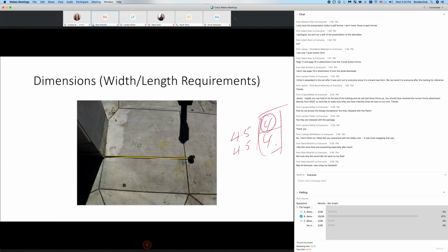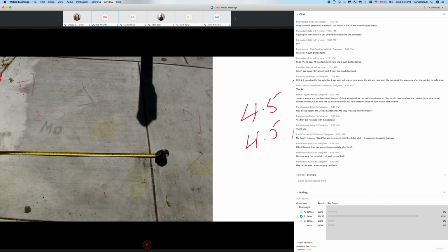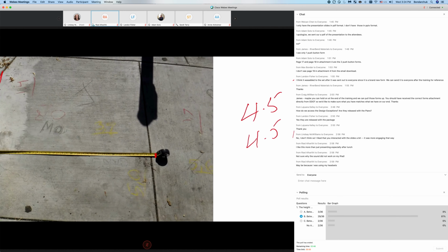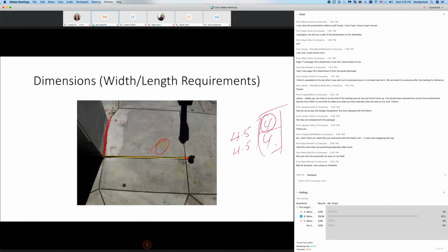And obviously here there are posts that are causing this, but you need to be checking this one out before you form it and make it, before pouring it too. So check this one out. Here it's obviously, here's a 4-foot mark. And this is right here, so that is a failure, and it's written here 3.9, so that's a fail.